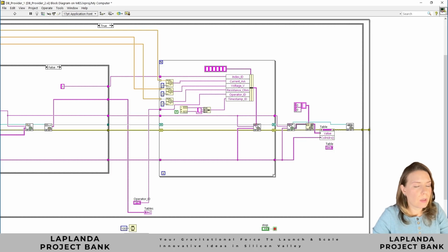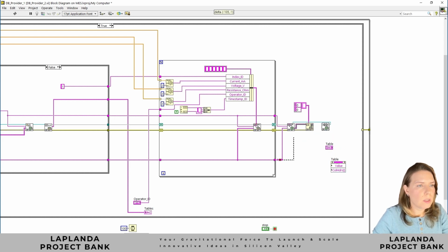efficient. At the final stage, we need to swap the positions of the property node and dbTools close connection function. Delete the old connections, move database close connection up, and place table property node last. Then do a little cleanup with cleanup wire and reconnect property node value and columns properly. Think of this as decluttering your workflow.